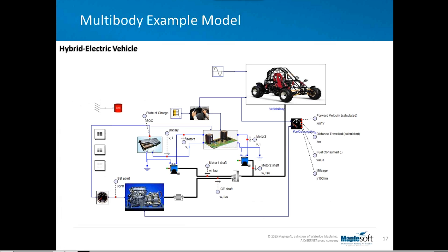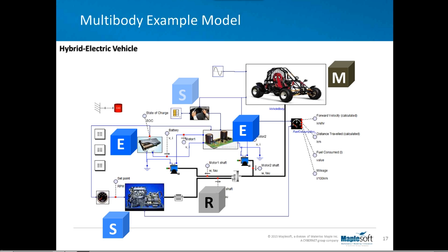A hybrid electric vehicle is another example that I mentioned here. The actual vehicle is a full multi-body vehicle model with chassis, suspension, and other parts. This gets activated through a drive shaft that goes through the drive line, or 1D rotational components. These get energized by electric motors. So there's a pair of motor generators in this hybrid electric vehicle.